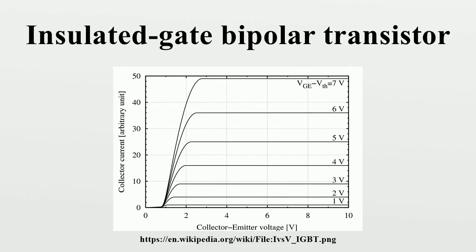Since it is designed to turn on and off rapidly, amplifiers that use it often synthesize complex waveforms with pulse width modulation and low-pass filters. In switching applications, modern devices feature pulse repetition rates well into the ultrasonic range, frequencies which are at least 10 times the highest audio frequency handled by the device when used as an analog audio amplifier.